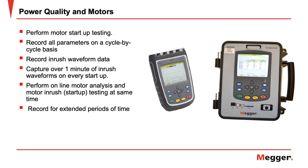The MPQ can also perform motor startup testing. The analyzer will record all parameters on a cycle-by-cycle basis, and when the motor starts up, it will capture over a minute of inrush current on all channels. And this is every time the motor starts. The unit allows you to perform online motor analysis and motor inrush or startup testing at the same time.